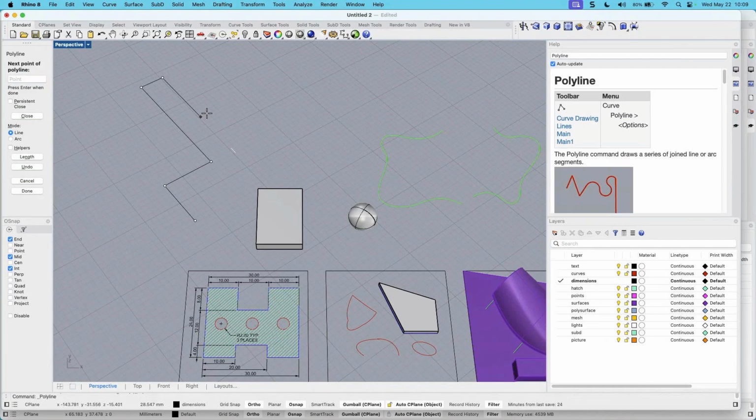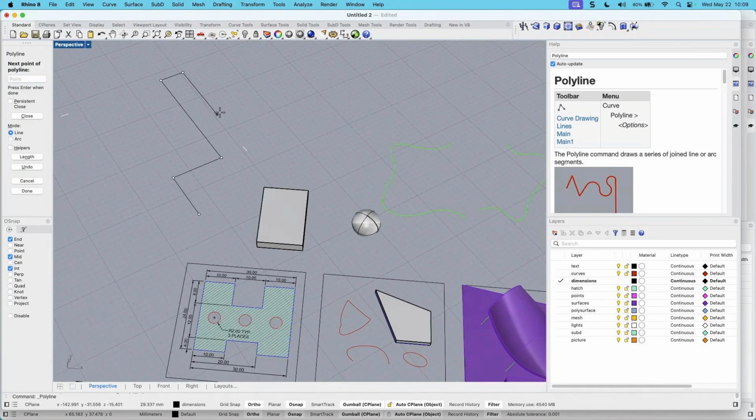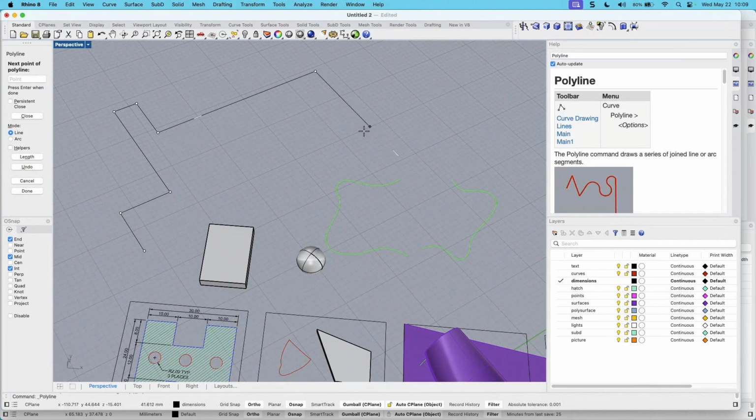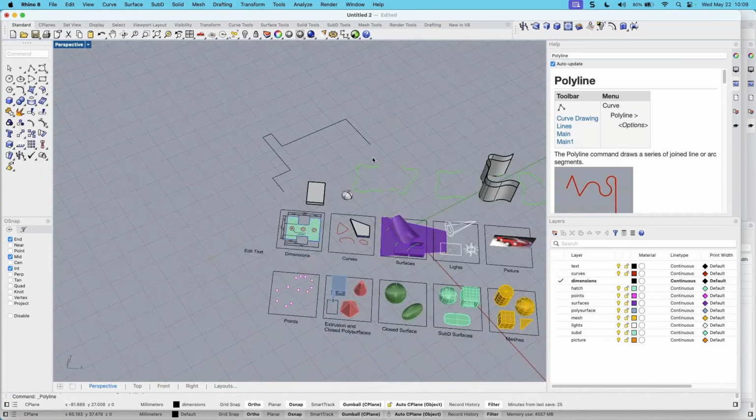So you can follow when you're drawing curves in Rhino, you can add a descriptor to the units that you're typing in, or the distance you're typing in, and Rhino will use that unit. So if I type in 3 inches with the inch mark, it will go 3 inches. I could use the foot mark here, but it would be pretty big for this model.